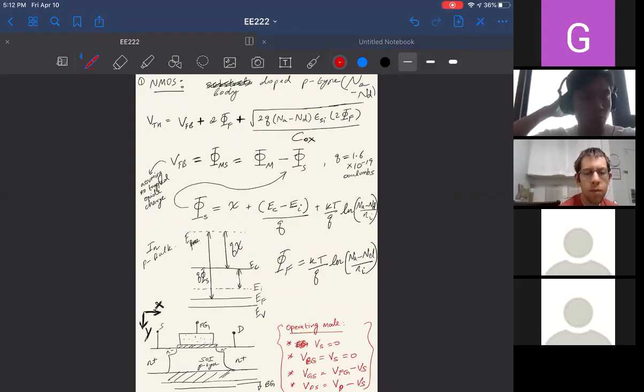I've summarized here the different equations that you need for the NMOS as well as the PMOS. For your project, you refer to the ITRS PIDS, which tells you what threshold voltage the transistor has. You choose a certain material for the gate, okay? The gate material determines, for example, the work function of the metal. You dope the semiconductor channel to a particular level, which determines the work function of your semiconductor. Then you choose a particular oxide thickness and oxide dielectric that determines your COX. You enter all these parameters here, and that gives you a threshold.